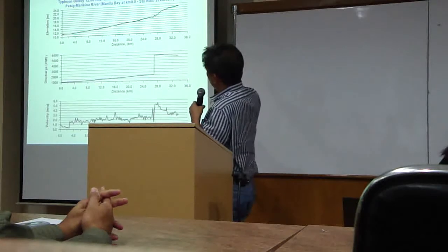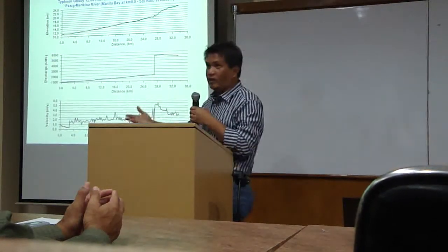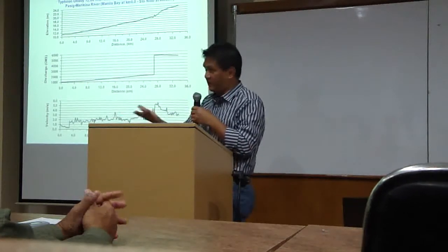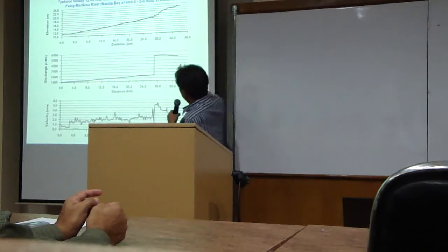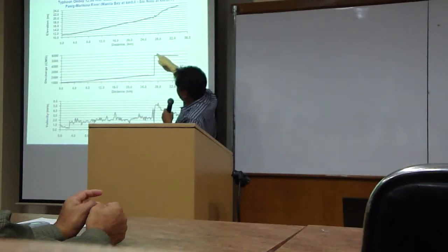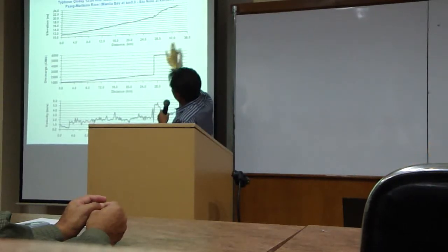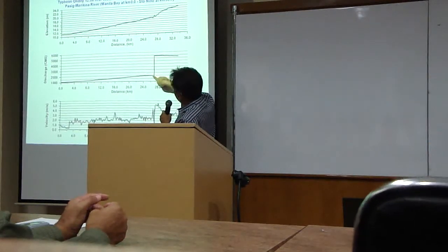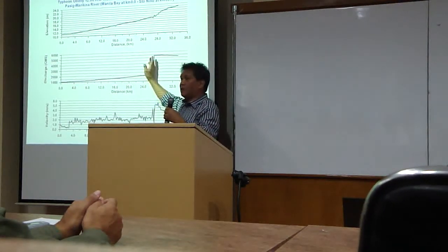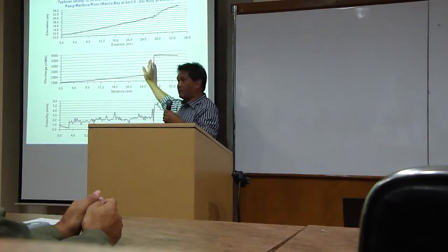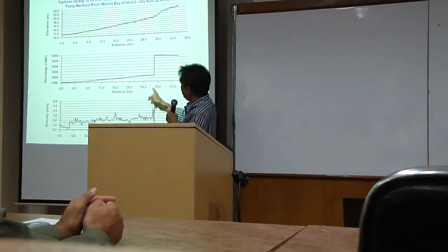So if you see 22 here, it's really 12 meters from the mean normal water. If you notice a big change in discharge, 5,000 around here, and then 5,300, 400, something like that. Then you have 1,000, 1,500 that went into Pasig River. So the remainder, which is about 3,000, went into the Mangahan Floodway. That's the reason why there is a Mangahan Floodway here.